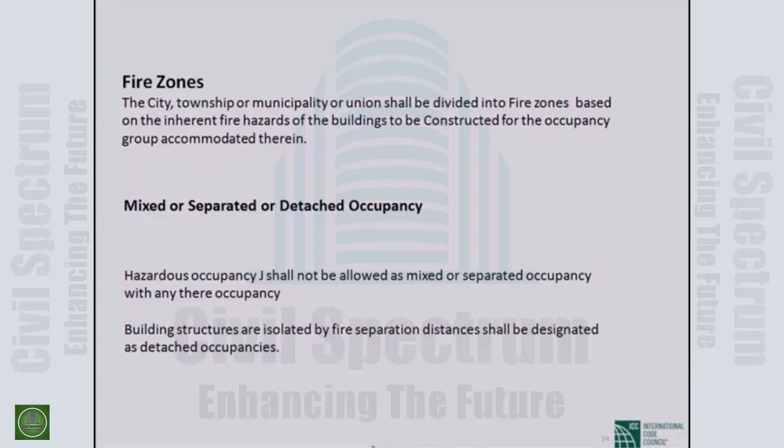For example, if in a building I have a residence, an assembly, and an office, the assembly has the critical data. If I allow all three to live together, I have to design everything depending on the assembly.